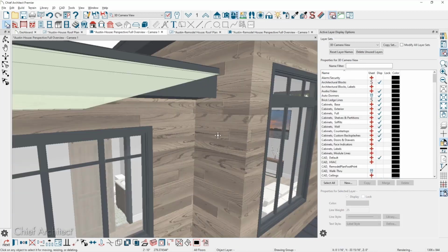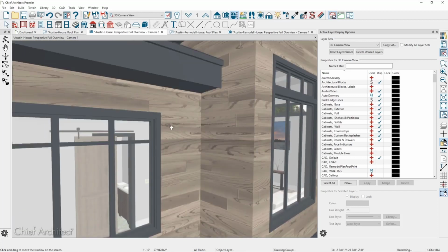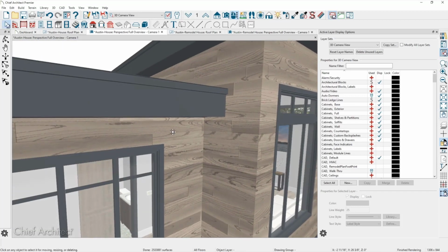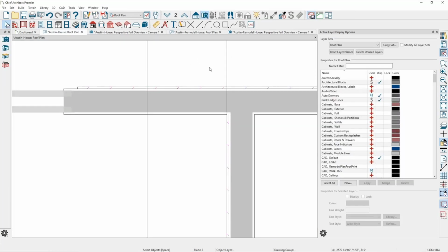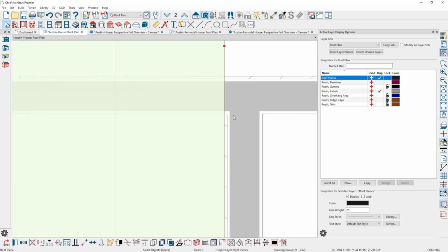Now, if I have a glulam beam that's running parallel to this supporting it, I can push that beam and have it sister right up next to the wall at the framing layer. It just so happens that I can't seem to push this roof into this gray layer, which is the stud. Right, the additional 4 inches of foam is the sticking point. Visually it works fine and everybody understands what's going on. It's just a matter of when you're going to generate the framing for it. I think Al probably has a better solution if you actually need to do it by changing the wall type. Go ahead, Al.